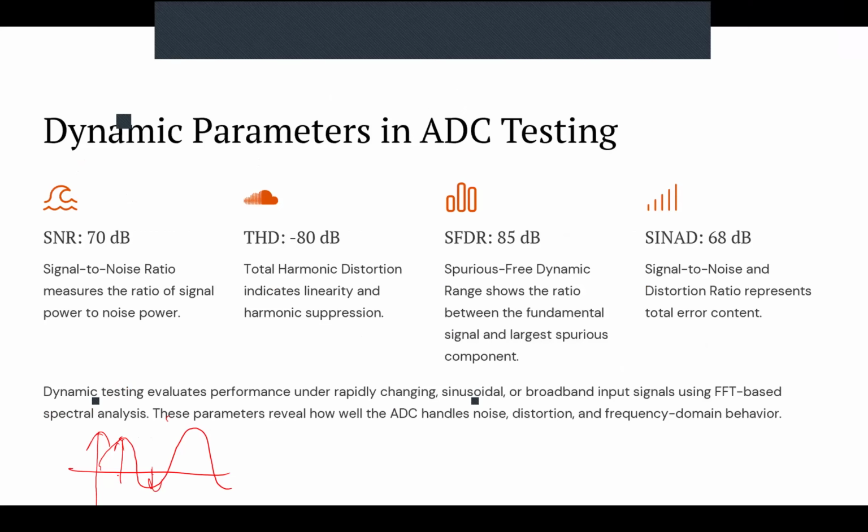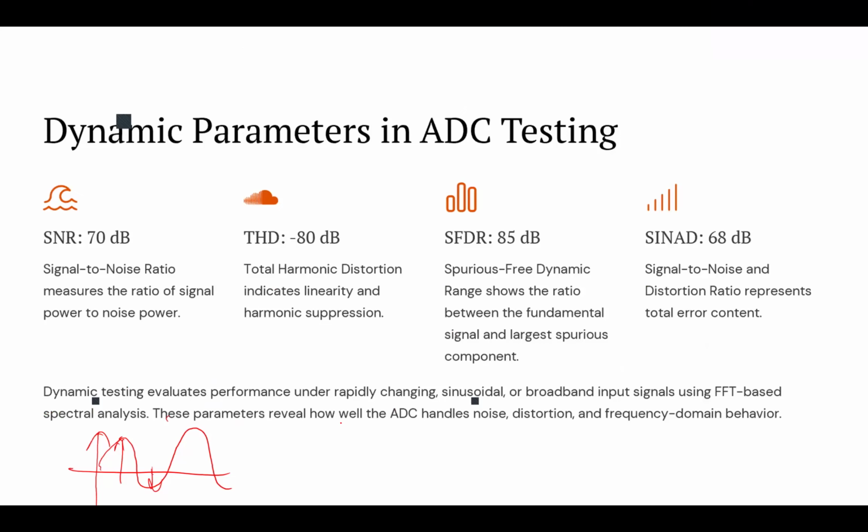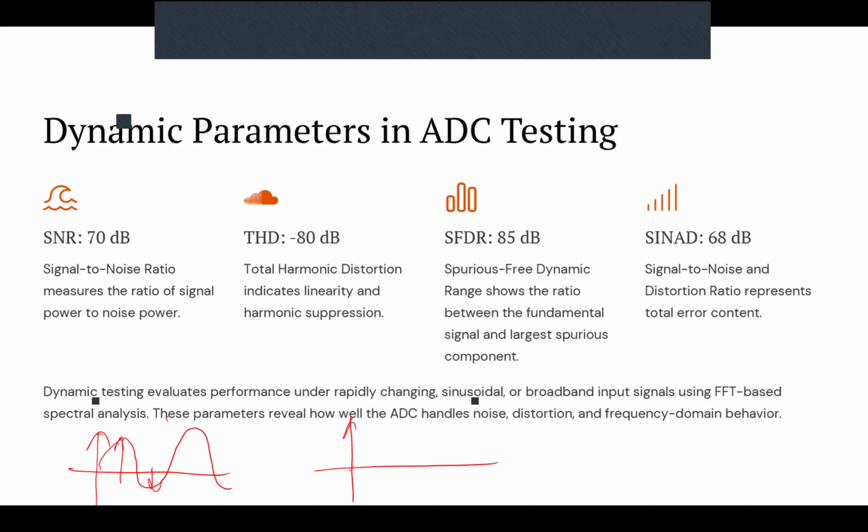Now we can reproduce the analog. But if we don't have a coherent sine wave as an input with the sampling frequency, for example, we have this, but our sampling is non-coherent, you can see that if we wanted to reproduce the analog signal, it would mislead us to another type of analog signal.